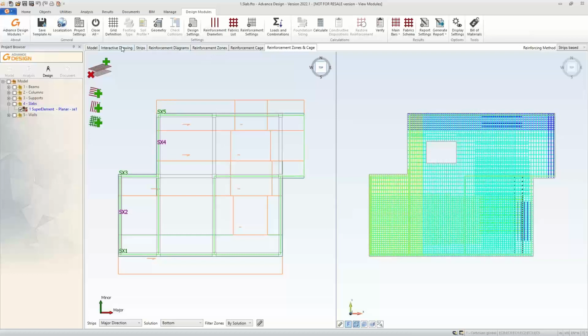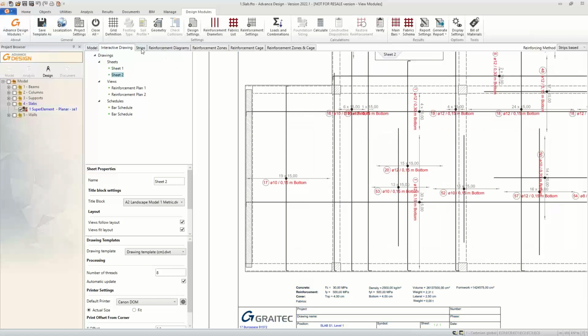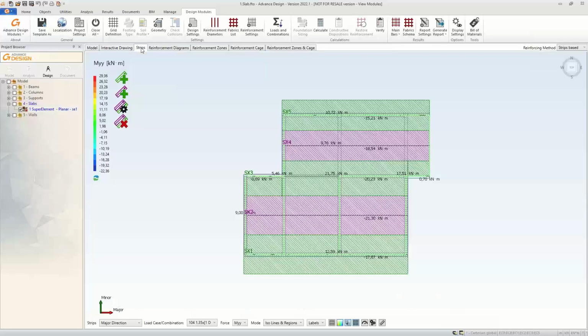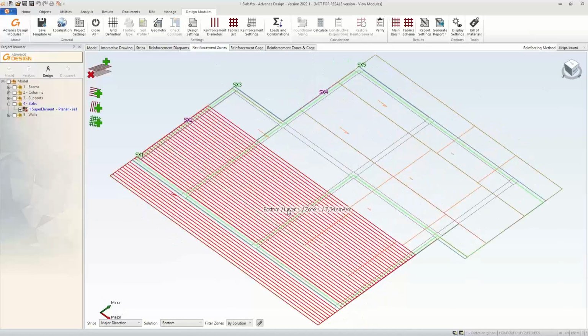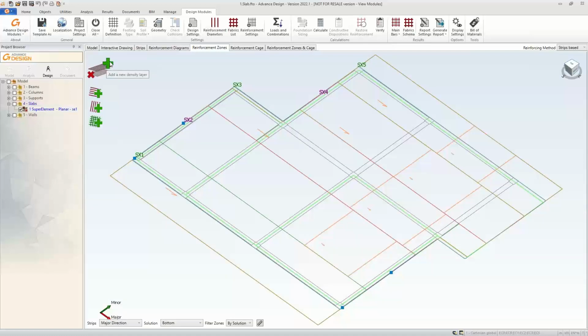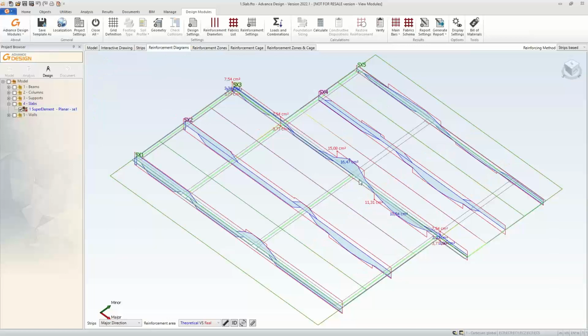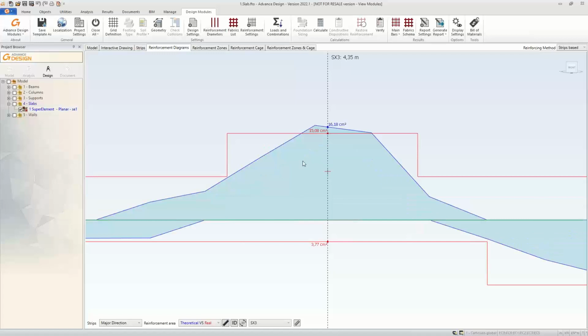For the strip method, the same rules related to drawings apply, so we get reinforcement. But for strips, it's important that any change related to the zone can be done even manually, in the same way as for classical reinforcement. What does it mean? I always need to check strips, and I see that there is a missing reinforcement area over there.